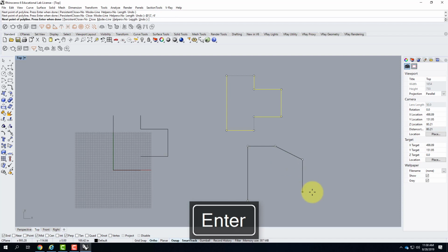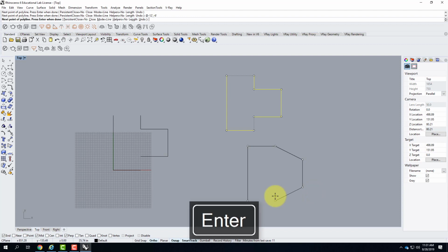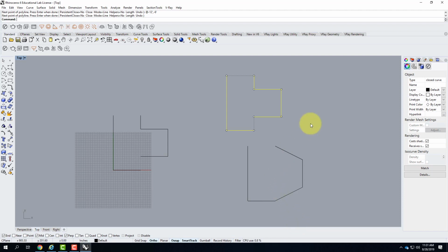So I can flip back and forth. So I don't always use all of one or all of the other. So there's 12 feet there, and this would be at -12 feet, comma, -6 feet, and then I could close it there. So depending on what shape it is that you're trying to draw, it's useful to have an understanding of what these coordinates are and how you can weave them backwards and forwards.